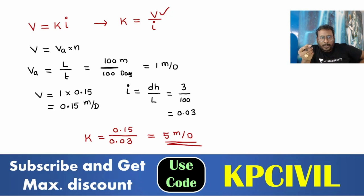Compared with porosity it is reduced to 0.15 meter per day. Gradient is equal to head by distance, 3 by 100, 0.03. Substituted in the K formula, 0.15 by 0.03, 5 meter per day, you got it.